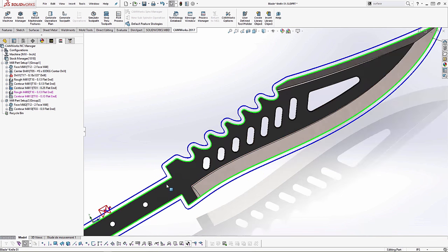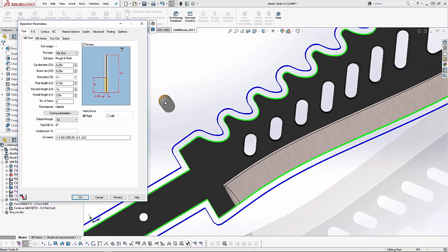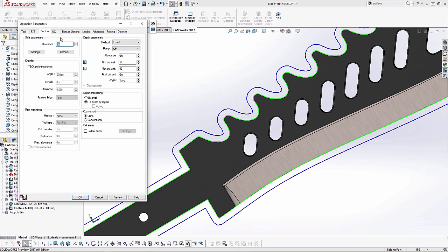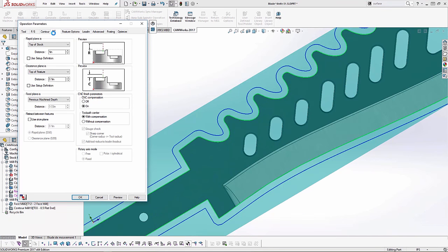More and more people are moving back to the old method of inputting the entire tool radius in the tool offset on their control. So in the beginning of CNC, it became very popular to use the CNC comp as a programming tool. Right? So if you had a 1/4" tool in your comp offset, you would put in 1/8", your full radius. And then people moved away from that, and it ended up being used as more of a